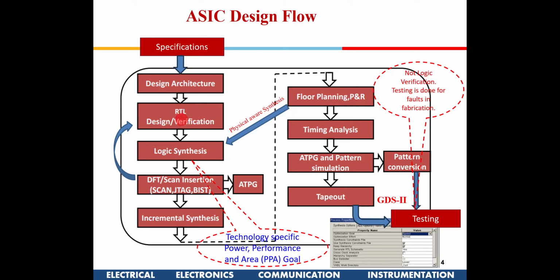After having done that, you go for logic synthesis. When you come to logic synthesis, what happens? So far this is just a code which is written. When I say logic synthesis, the tool will try to implement that with gates. The tool needs to be given a library file for all these gates, generally from the manufacturer. Some manufacturers provide technology files, like for LTspice we use 180 nanometer technology. Similarly, in logic synthesis, say 180 nanometer gate models will be given, not the transistor models, the gate models. Based on the code which we have written, it is going to synthesize this logic.